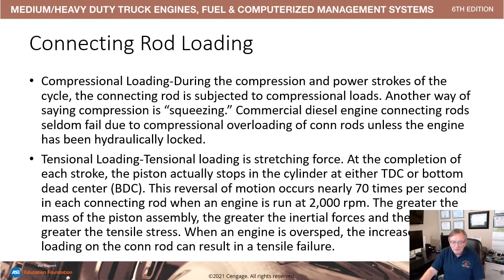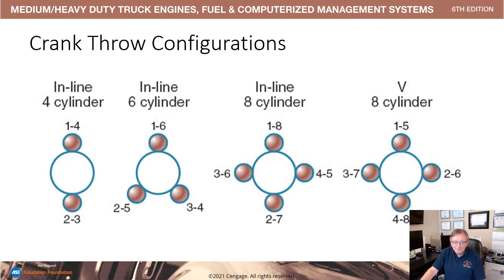Connecting rod loading. We have compression during the compression and power strokes, and we have tensional loading, or stretching, from top dead center to bottom dead center. This occurs many times per second when the engine is run at normal speeds. Engine overspeed will cause a connecting rod failure.